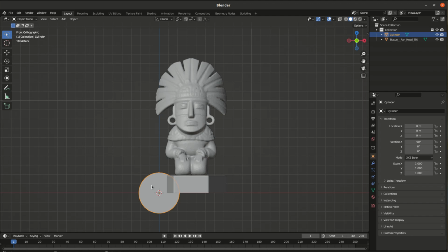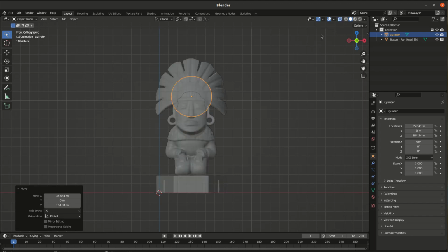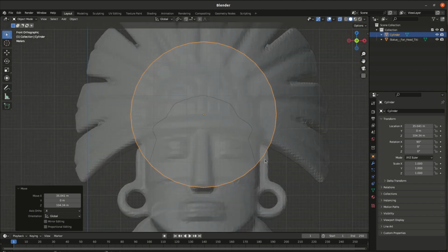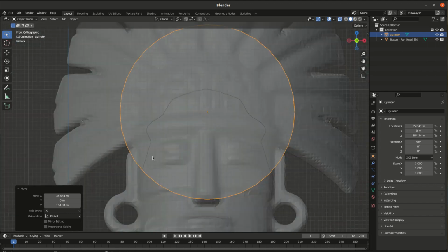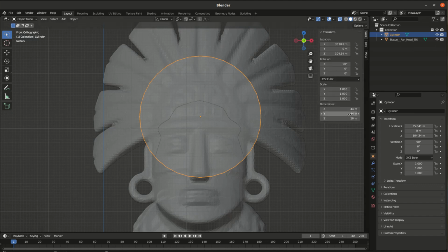So let's move it with G. Okay, and since we want to move it inside the surface only, I'm gonna choose Y. So you see now it's gonna move along here. Let me put it to X-ray so it's easier for us to see. All I wanted to do is make sure that it won't cut here, here, and this side too. I can see maybe I'm gonna make it a little bit bigger. Okay, so instead of 44 I'm gonna put 45 on both sides.